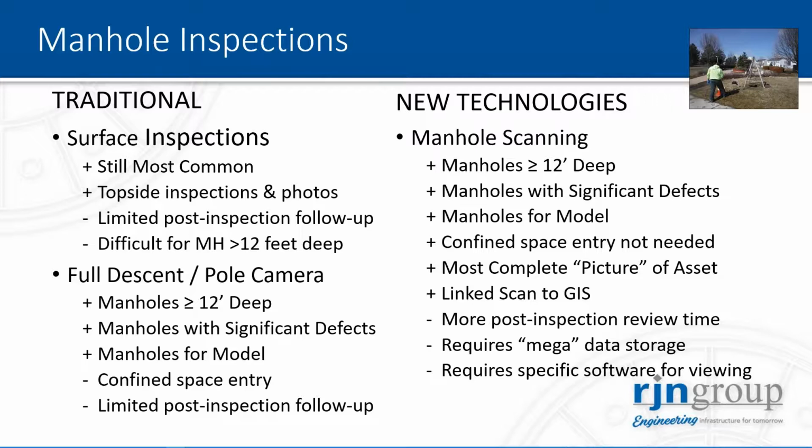In traditional inspections, a few items to note is that it's very quick in terms of just doing surface inspections, but on deeper manholes, you will be required to do full depth inspections. And the challenge for full depth is you do need confined space entry.